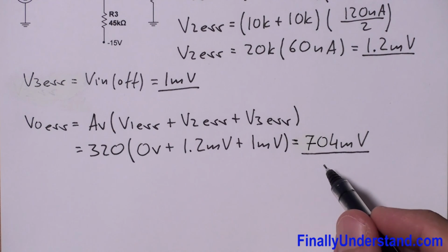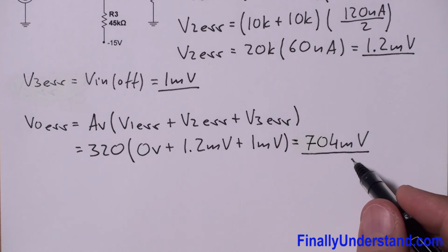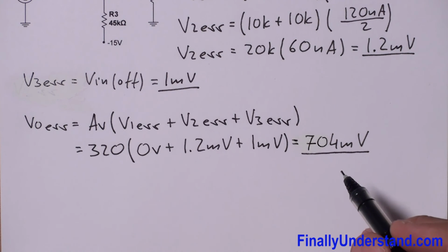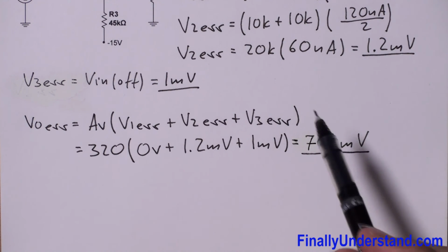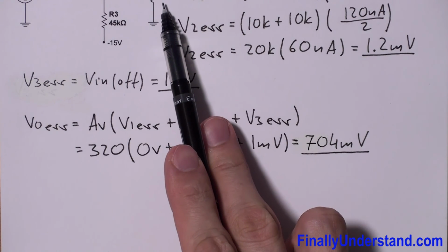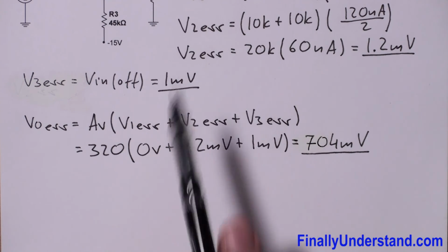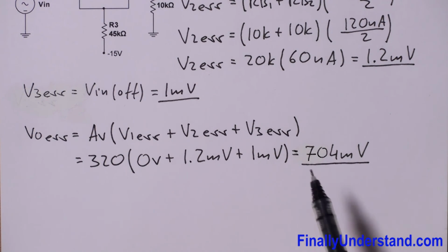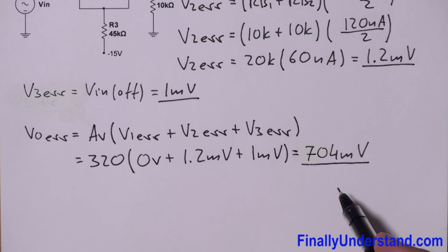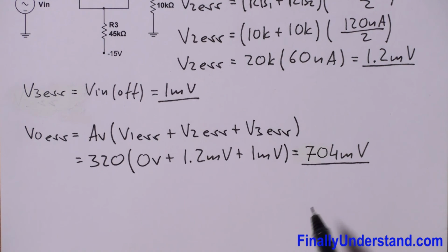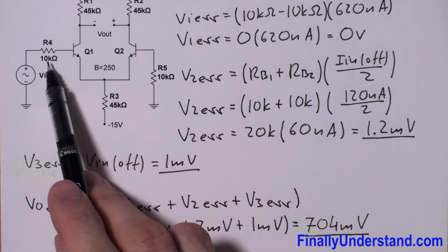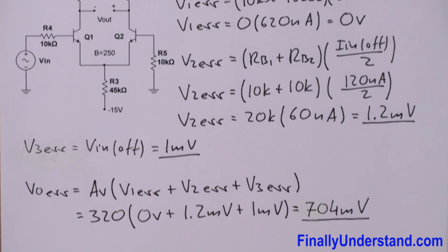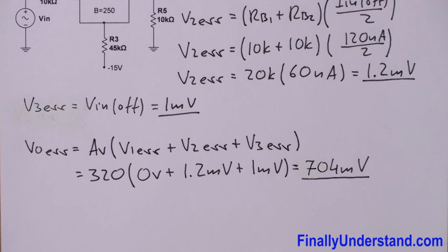If we are going to compare this result with the result which we got in the previous problem, you will see how much error voltage has been reduced by adding simple resistor R5, okay, to the inverting input. So now we can say that this amplifier has much better performance than the previous one. So using the matching resistors is the way to reduce the output error voltage. Now I can say that the problem is solved.